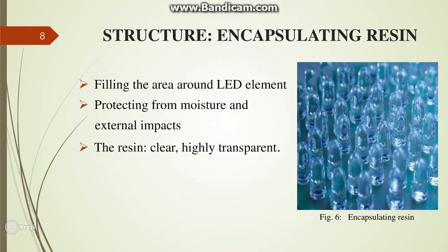The fourth component is the encapsulating resin. Here is the image of it. Usually we use plastic to make it. The encapsulating resin fills the area around the LED element. This protects the LED element from moisture and external impact. The resin is either clear or, at a minimum, highly transparent to the emitted light wavelength.